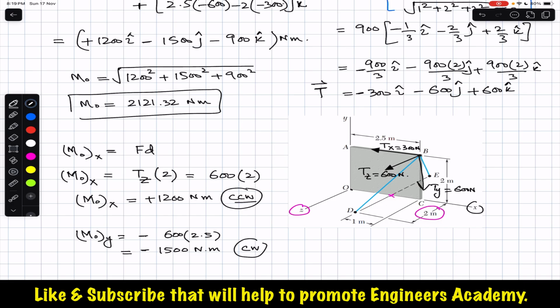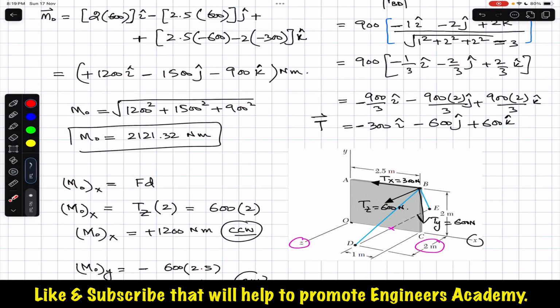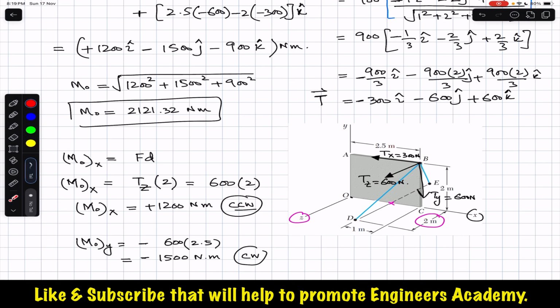So the minus sign means that this is in the clockwise direction. This one was in the counterclockwise direction. So as we can see, here the y component of the moment had a magnitude of 1500 Newton meter, and we had a minus sign. So this is the same. The minus sign tells us that the moment at O about the y-axis is in the clockwise direction.